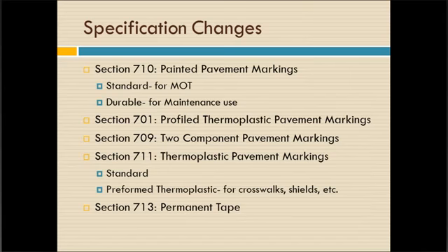Some of the specifications that have changed to coordinate with all these bulletins include Section 710, the painted pavement markings. Before, you probably just referred to that as the paint for MOT, and that was our standard paint. We've also added in the durable paint, and that's primarily for maintenance use.